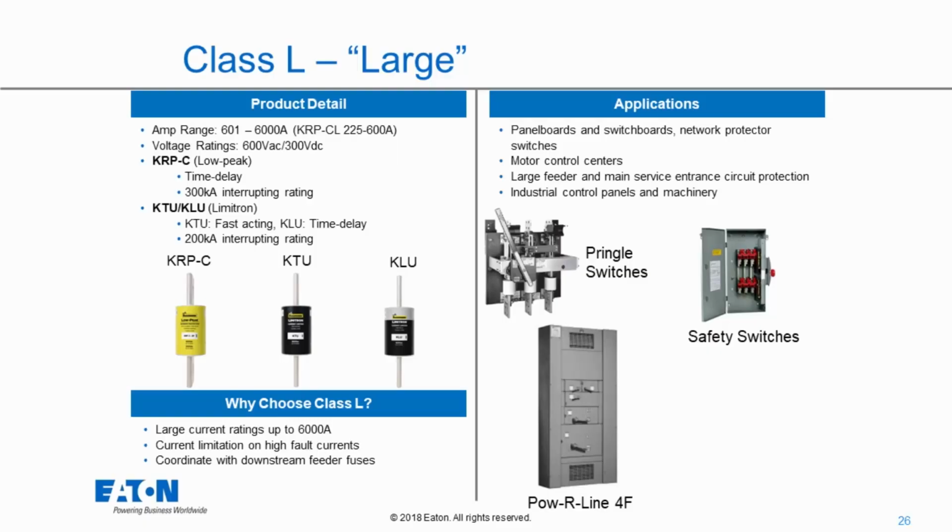It's very rare I put these in their own fuse holders. Typically, what you're going to mount these to is either a switch or some kind of busway in your system. So it's very rare that I'll get a call for fuse holders themselves. In this particular case, it's usually a system already designed to house these larger fuses. Typically, in some metropolitan areas we'll get some very large ones, 4,000, 5,000 amp units, but in general, you'll see a lot of 800 and 1,200 amp units around in many systems.